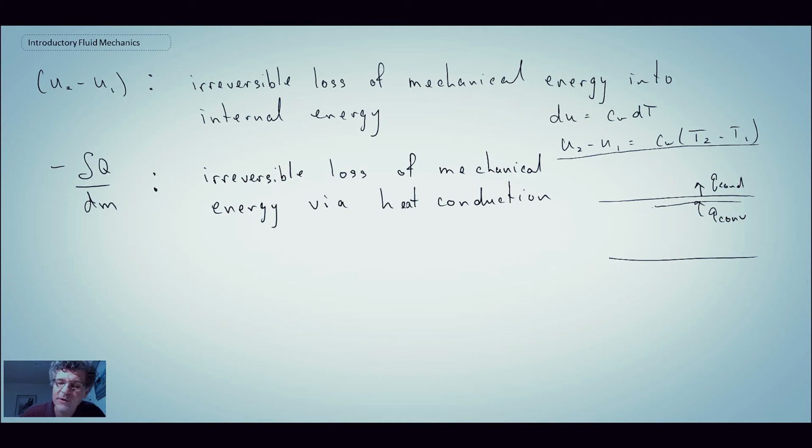So pressure, which drives the flow, goes into kinetic energy, which goes into internal energy, and that then goes out through heating up the internal energy of the soil around it, or the air, through conduction and convection. That is the process by which energy is lost in pipe flow, and where the energy is going.